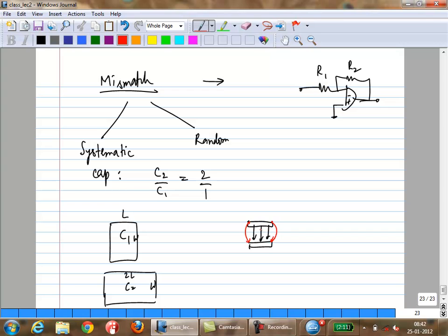Everywhere else inside, you have metal plates on all sides. Electric field lines have only one way to go, right? Out here suddenly you have a sudden mismatch, a sudden change in conditions. So what happens? Eventually the field lines will end up at the other plate, but you have fringes. Same thing here. You're going to have fringes on this capacitor also.